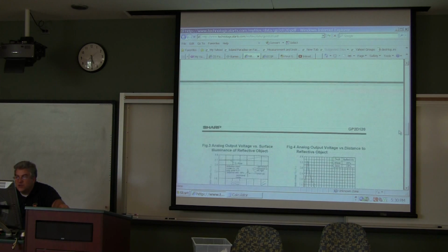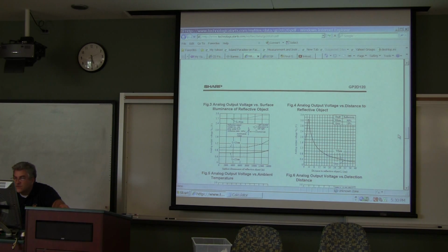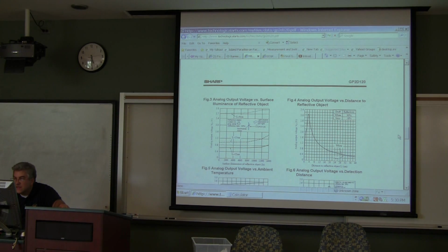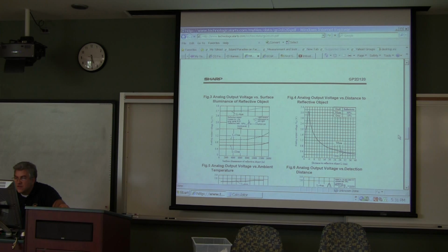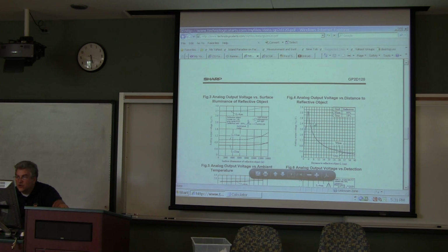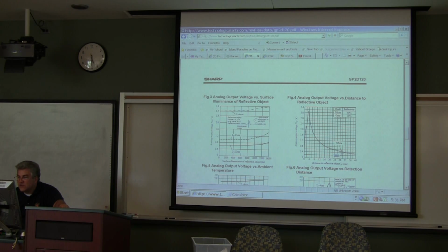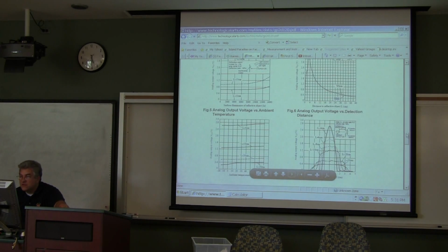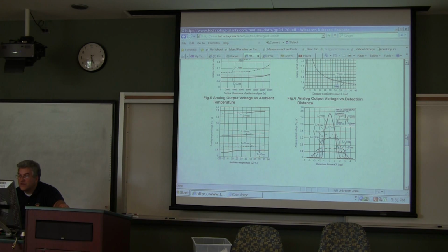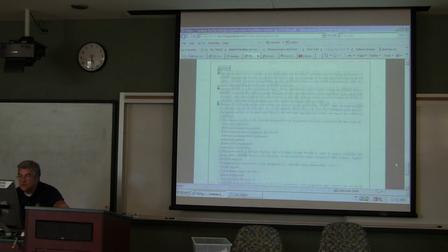I'm looking for the formula of the curve. Analog voltage. Distance reflected. This is a nicer curve. So you notice here it says 2.8 volts. And down here, which is where they're recommending the distances at 30 centimeters, it's down to 0.4. And they even have a different value for white and gray when it gets towards the end. Where's my formula? Where's my formula?